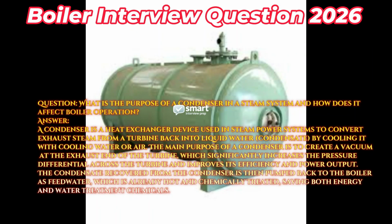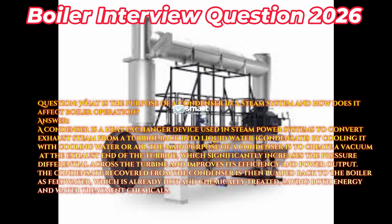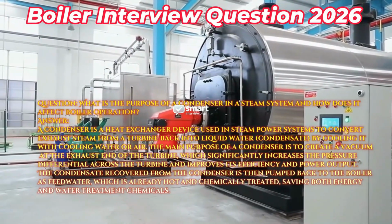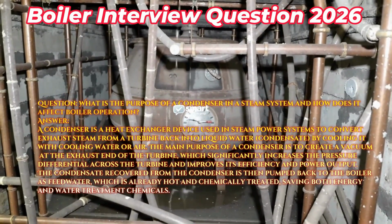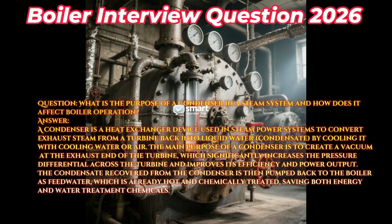Question: What is the purpose of a condenser in a steam system and how does it affect boiler operation? Answer: A condenser is a heat exchanger device used in steam power systems to convert exhaust steam from a turbine back into liquid water, condensate, by cooling it with cooling water or air. The main purpose of a condenser is to create a vacuum at the exhaust end of the turbine, which significantly increases the pressure differential across the turbine and improves its efficiency and power output.